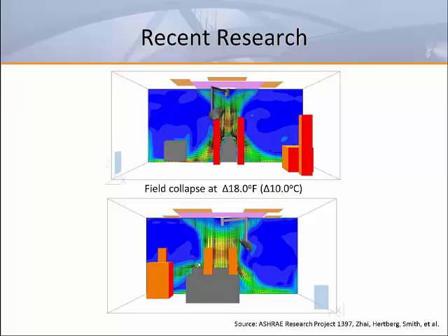This presents an issue as on the perimeter of the sterile field, that velocity is now much higher than originally intended, with the 25 to 35 CFM per square foot entering the space. As the flow accelerates, you're going to be pulling more air to entrain along that flow, which pulls it in and potentially dumps that contaminant or pathogen onto the wound site or onto the instrument table.